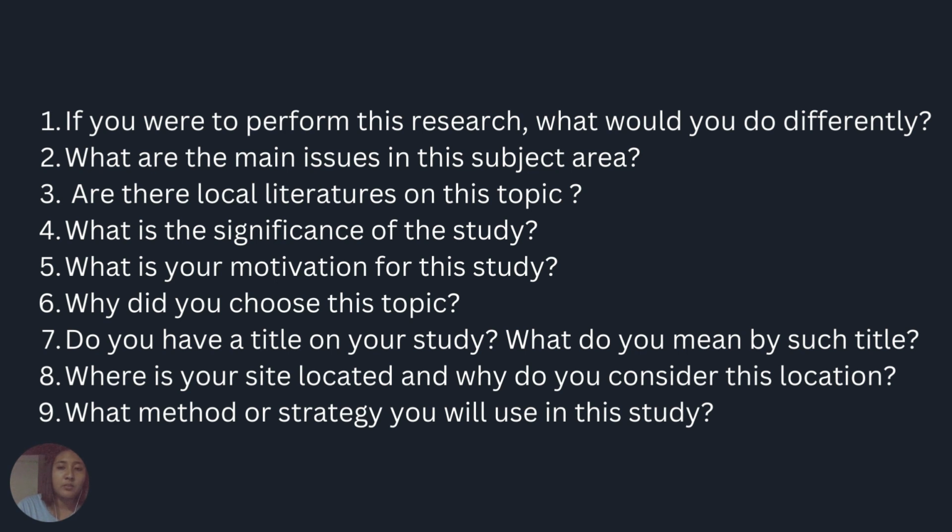Until now, our country's problem in plastic waste has no concrete solution. That's why we need an evolutionary solution that will help reduce these tons of plastic rapidly. And I believe using plastic waste in asphalt road construction will help reduce our problem in waste. Research has indicated that the addition of polymers to asphalt binders helps to increase the bond between the aggregate and the binder, which can enhance many properties of the asphalt pavements.